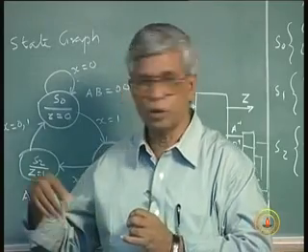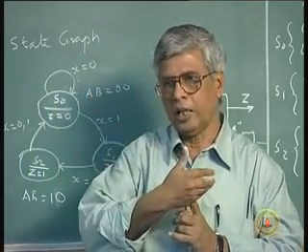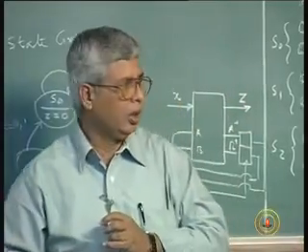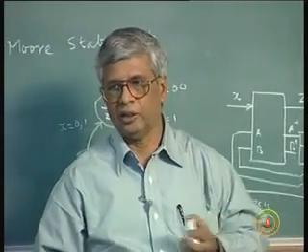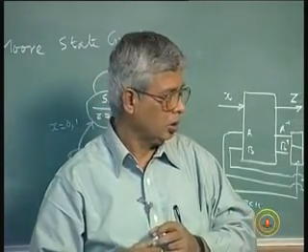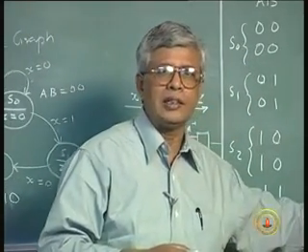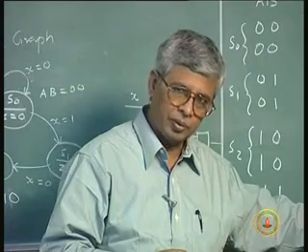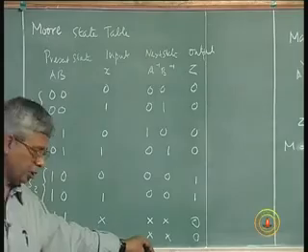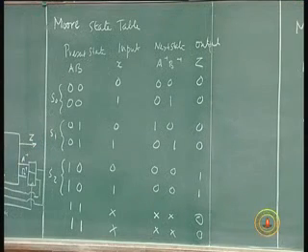In both cases, you should indicate the outputs in the state graph, carry it into the transition table, state table, and into the graphs, Karnaugh maps, and in the final logic that we design for the hardware. Now, with this background, we will now consider systems. We will have outputs which are other than the state outputs or state variables. We will take some examples.